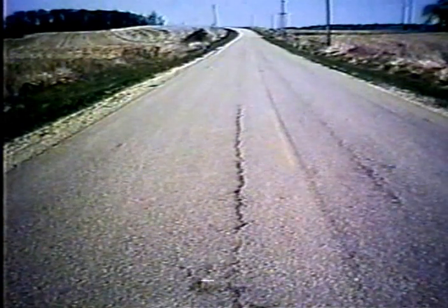It really pays to pay attention to the construction details and get good compaction on our longitudinal joints. Because if you don't, this is a real maintenance headache. You've got a pavement that's essentially in good shape with one narrow strip that is now causing you problems down the middle, and it's very difficult to treat from a maintenance standpoint.